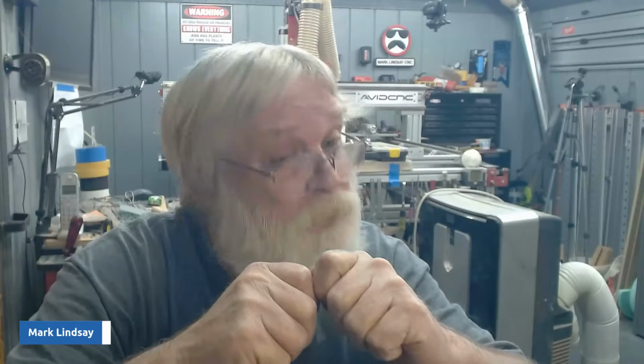The easiest way to do that is to disconnect the cable and make certain, before you disconnect or connect any cables, you've turned the CNC off. That controller needs to be turned off. If you're not certain, unplug it. It's got to be turned off. You can easily fry a motor if you apply power to it by unplugging or plugging it in. I've seen it happen. Make sure it's all turned off.